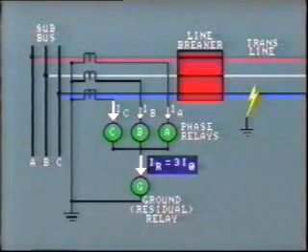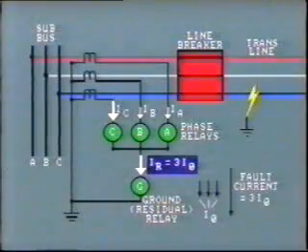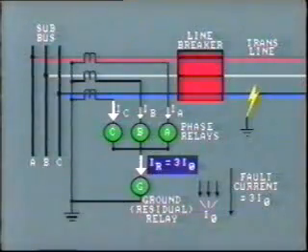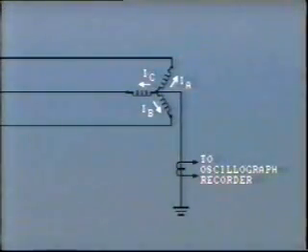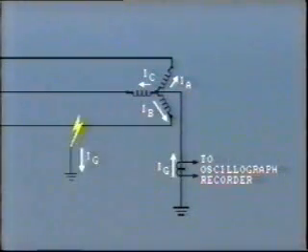You will often see the residual current expressed as 3I0. Remember, the magnitude of current for a single line-to-ground fault is just 3 times its zero-sequence component. Another very sure way of detecting ground faults is to monitor the current in the grounded neutral of a Y-connected transformer winding. Again, this current is quite small under normal, balanced conditions, but rises significantly when a ground fault occurs.